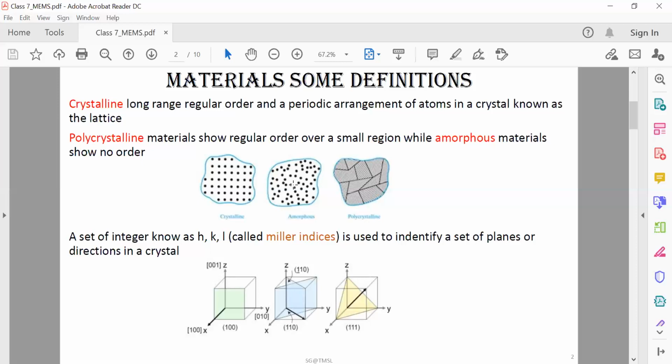One example is, if you evaporate a certain metal film on a single crystal silicon substrate, then this film is an amorphous film. For example, if you implant silicon with certain ions in an ion implanter, the regions where the implanted species will locate will initially be highly amorphous. After that we have to do sintering or annealing, so that you again get back the regular silicon single crystal structure. So those are the amorphous examples.